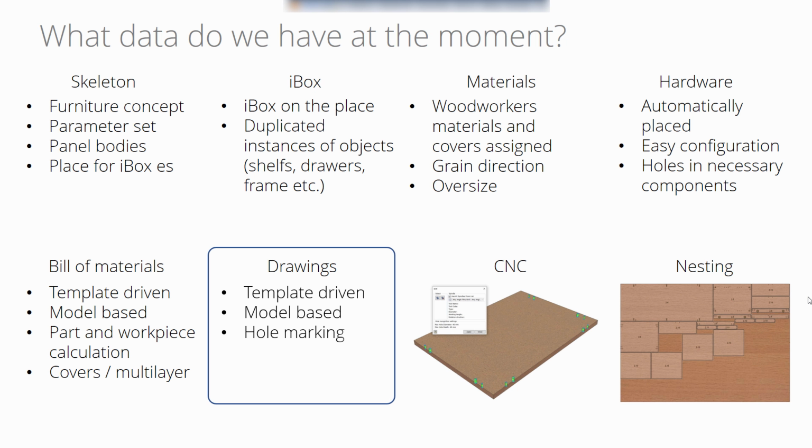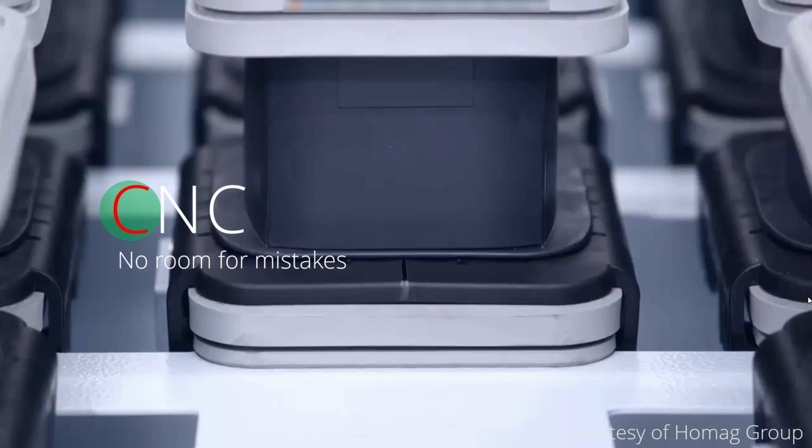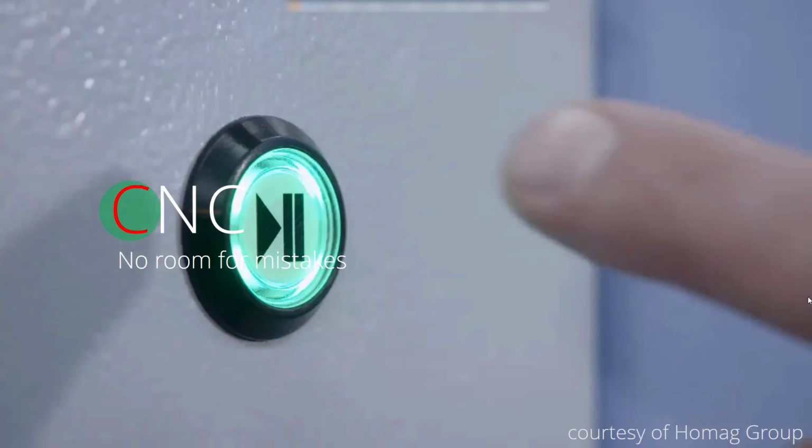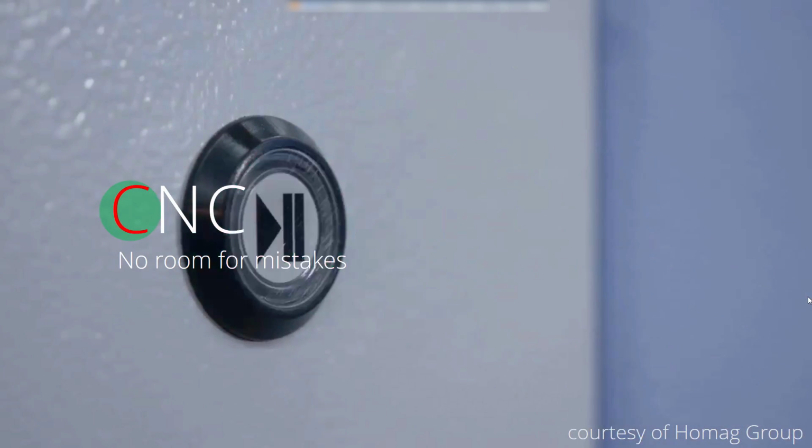So in terms of the drawings, they are template driven and model based, like the bill of material. You will get basically all the information you need for the production of the drawing automatically. So you get the grain direction, the hole annotations, the part and workpiece sizes, hole coordinates, and so on. So now it's time to speak about the CNC. It's computer numeric control.